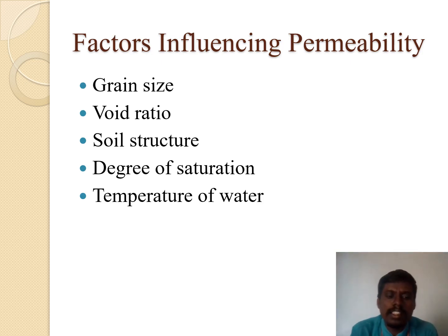In the constant head permeability test, the soil sample is connected to two tanks, one an upper tank and the other a lower or bottom tank. The two tanks have different levels of water. From these two tanks, the water percolates through the soil sample. Based on that, we note the level difference H1 minus H2 with respect to the time differences. At time intervals T1 and T2 we get H1 and H2. Based on that, we calculate the coefficient of permeability.